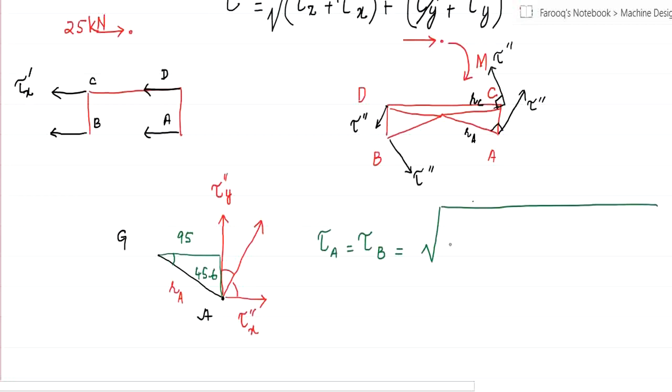So we are going to write the X component 19.5, X component of primary stress plus or minus X component of secondary stress, and we know that these two X components are in different directions, so that is why we will have to plug minus here. 19.5 minus secondary shear X component, sine 25.64, plus Y component of our secondary shear 41 cos 25.64.